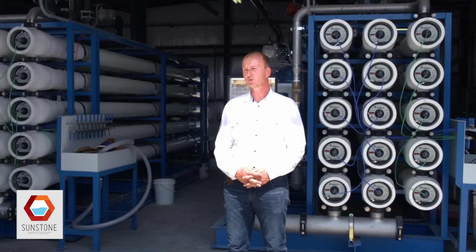There are problems when you do desalinations. If it was only salt that was in the water, the RO membrane will work quite nicely. Often there is a large amount of calcium, manganese, iron, and there can also be organic matter. And that means that these membranes here will actually get scaled or fouled, and that means that the pressure drop over this membrane will get high, and it's very expensive to run these ones. At the same time, you need to clean them very often, just to be sure you're getting water through the membranes.